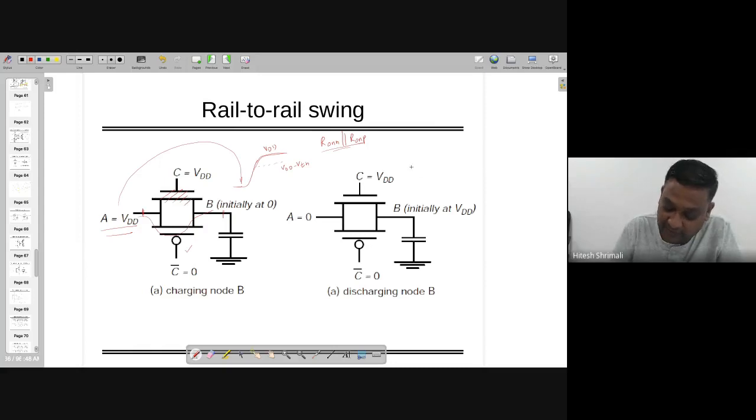And the same thing will happen when it's going from VDD to ground. Till VTP, this PMOS will act properly, but afterwards this NMOS will take care of the logic, going to 0 by its own characteristic of sending a strong 0 to the other side. So that is what we are doing, and we are getting the rail to rail swing. So for all implementations of CPL, meaning complementary pass transistor logic, you can use such transmission gates so that you can have the output as you want.